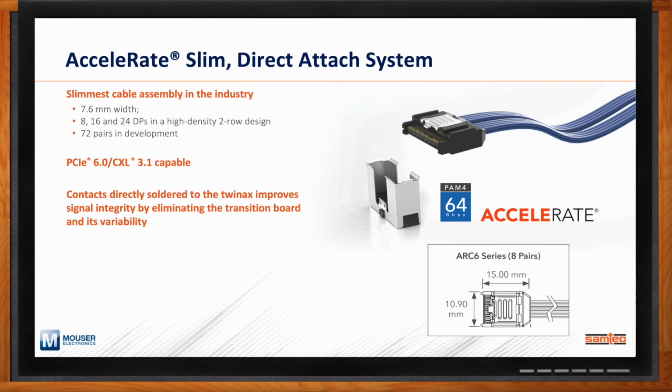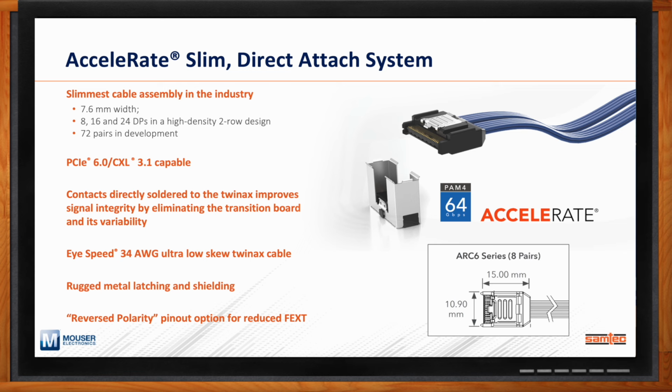So Accelerate Slim is another example where by having that direct attach, you improve the signal integrity, eliminating the transition board that's typically found in these types of solutions. Accelerate Slim also takes advantage of our ultra low skew, high performance, I-speed 34 gauge cables. The solutions can also be ruggedized with metal latching and shielding, especially for embedded applications. We also have reverse polarity pinout options that will reduce far end crosstalk.